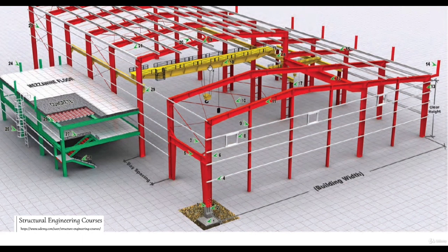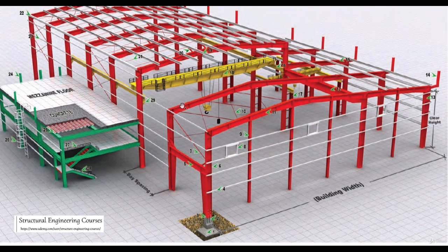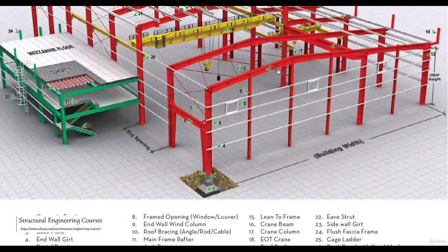The purpose of this EOT crane is to lift anything from the ground and transport it all the way, for example, from this point to this point. And how we can transfer from this point to this point, we usually provide some rail sections here. The rails are the same rails that are used in the railways also. You might have seen those sections like this. So we provide rail sections here, and on top of those rails, with the help of the wheels, this EOT crane may move from this point to this point. But to support those rails, we do need some beams also. These are called the crane beams.